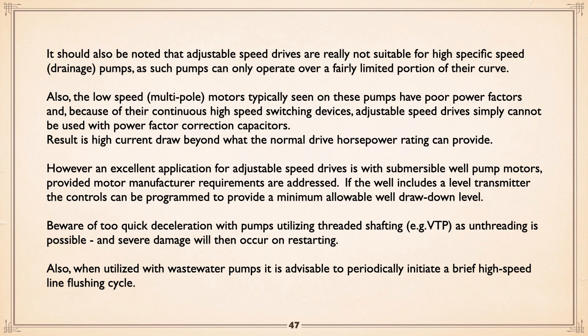But if you have too quick a ramp down, the drive will force the motor to follow it, unless you have the drive set up to turn off. If it slows the motor too quickly, the inertia of the pump will take over and unthread the shafting. Then when you go to start the pump, it takes up that slack with a hell of a bang, and you can do damage.